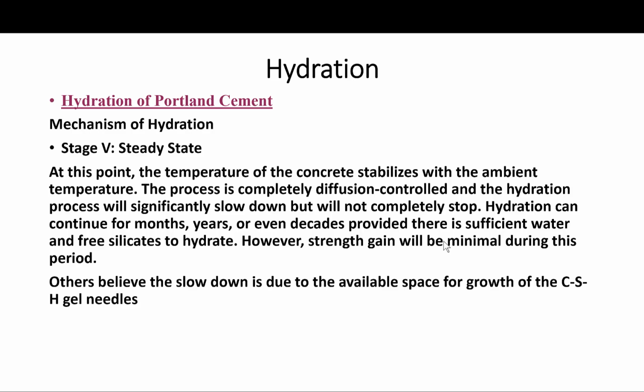So remember that. The idea of studying this is to relate it to practical purposes and what you see in the field out there, how the concrete behaves. The idea is to relate it to the science behind it. Okay? So hydration can continue, as I said, for months, years, or even decades, provided there is sufficient water and free silicates to hydrate. That's why, again, curing is important. But strength gain will be minimal during this period. There will be strength gain, but minimal. Nonetheless, it continues to hydrate.